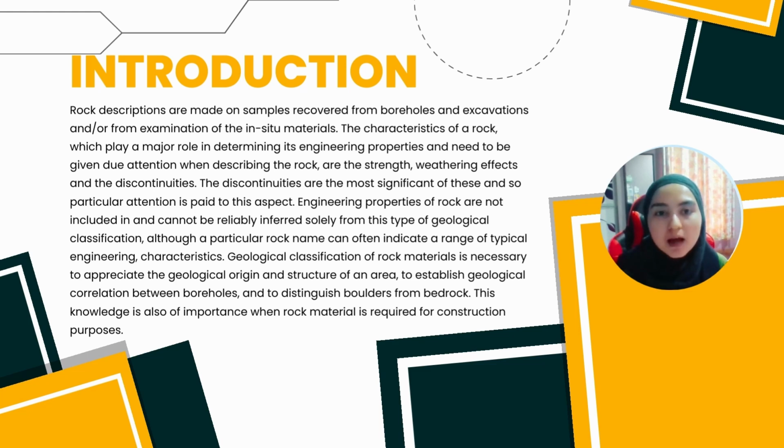Rock descriptions are made on samples recovered from boreholes and excavations and/or from examination of the in-situ materials. The characteristics of a rock which play a major role in determining its engineering properties and need to be given due attention when describing the rock are the strength, weathering effects, and the discontinuities. The discontinuities are the most significant of these, and so particular attention is paid to this aspect.